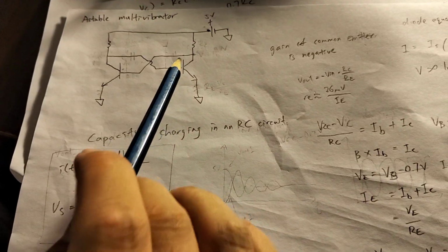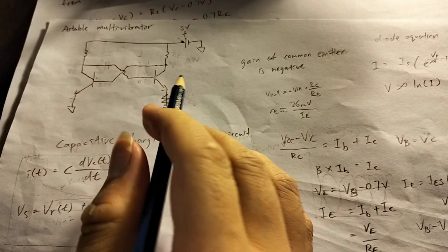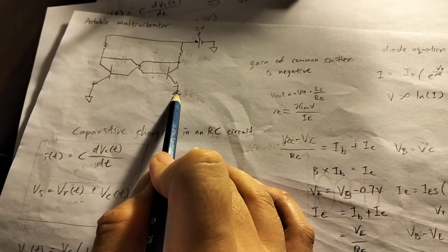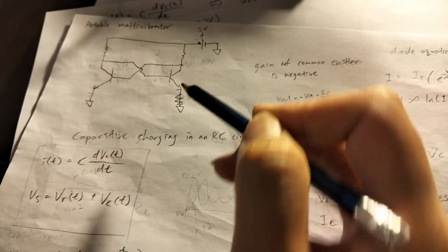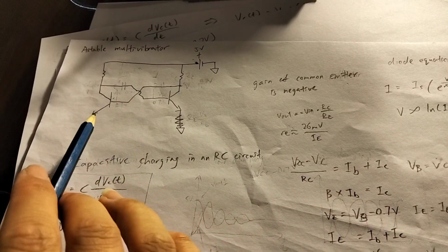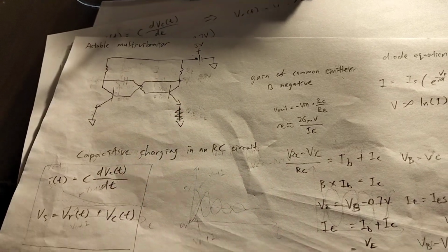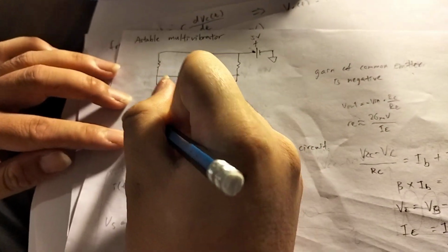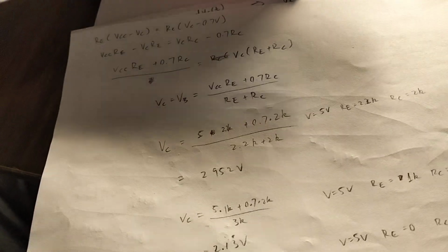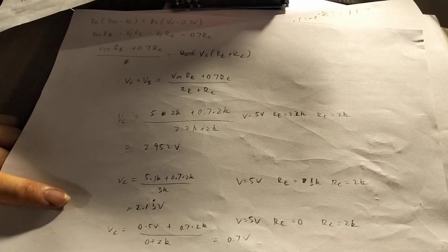Let's say we put an emitter resistor here. If the emitter resistor is large, RC over RE becomes less than 1. So it becomes a decaying effect and does not cause a runaway. If we have a large emitter resistor, and I breadboarded this before but I'm not going to show that, it runs through these equations that create an equilibrium state.